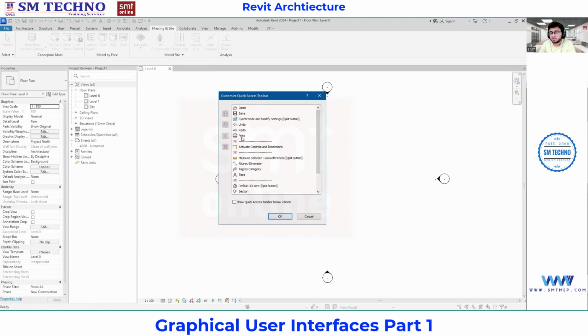You can arrange as per your order, like open, save, synchronize, undo, redo, print are under one category. This horizontal line, what you can see, is called a separator line, which will divide the entities. Like in AutoCAD, we have got the modify commands as well as the drawing commands. So same like that, here also we are having the segregation. So if you want to remove this segregation, you can select the line and delete it as per your wish. If you want, you can keep or else you can hide.